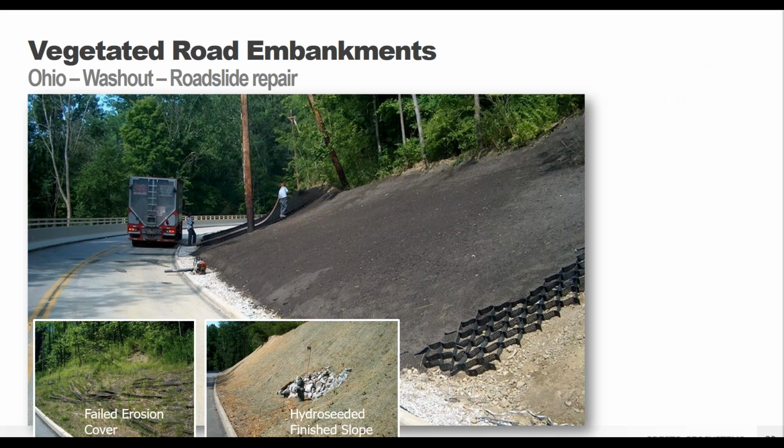So this next one's a really common application. Road embankment repairs. You're constantly seeing soil or stone wash out onto your roads, potentially closing lanes, just causing headaches for everybody. So by covering the slope with the GEOWEB system, and then you fill it in with topsoil, let it grow, get that nice vegetation in there, now you don't have to have the concern of constantly replacing the soil after storm events. You don't have to constantly come in and clean off the road, that sort of thing.